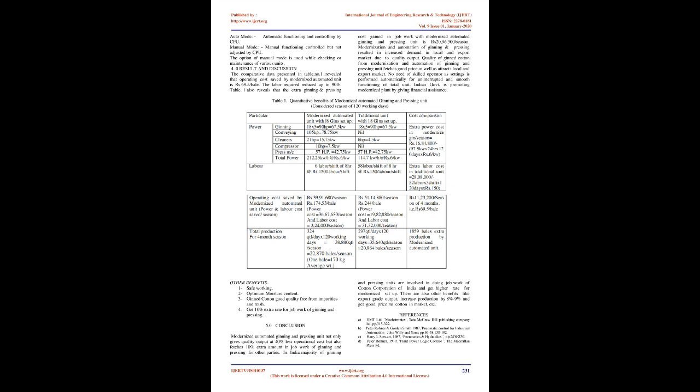6. Auto-operated firefighting system. Fire hazard is greater in the case of cotton, so there is an urgent need for an automatic firefighting system. The spraying system installed has a provision of quartzite bulbs. In case of fire, the temperature rises and the bulb breaks, giving a signal to the controller, and the system starts automatically.